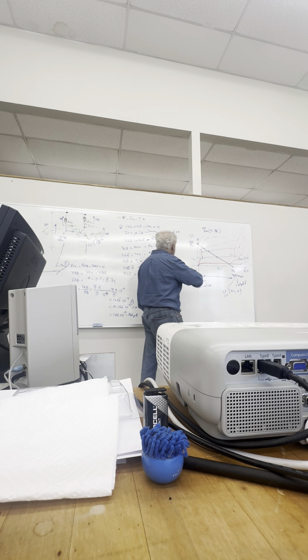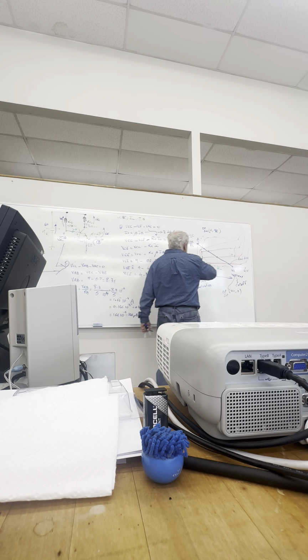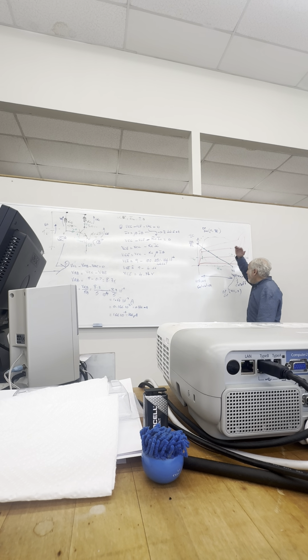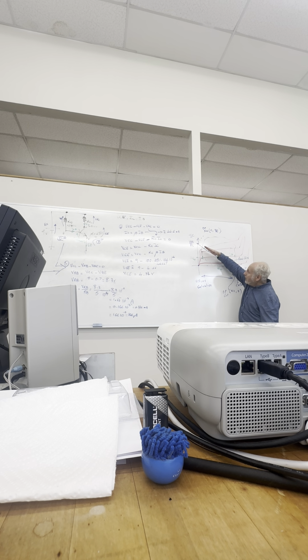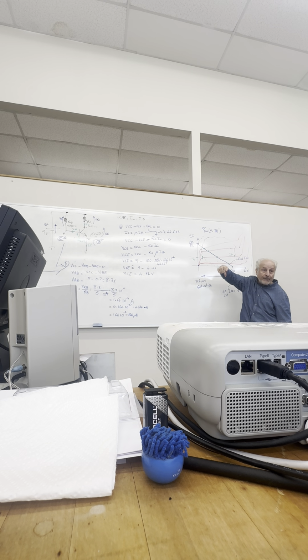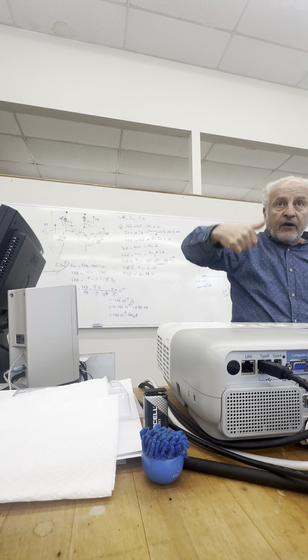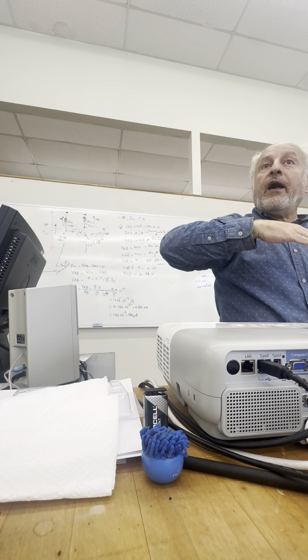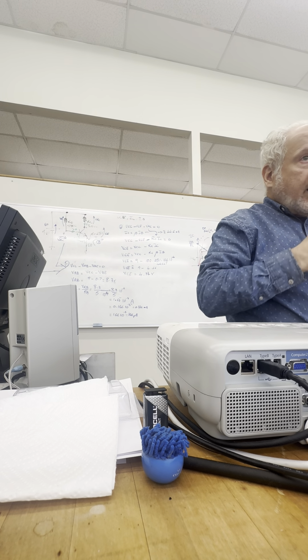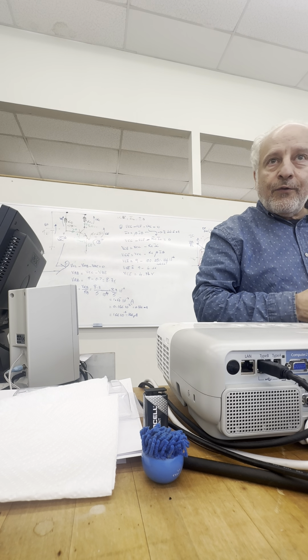So how would I control that? Well, that's perfect. I could use a circuit like this. I know my fulcrum is here, and I could put a potentiometer there and just move up if RC goes down, move down if RC goes up. Why? Because IC goes down. Does that make sense? Right, so it's an inverse ratio of RC. RC goes up, IC goes down. And I can control where I want to be. You with me so far?